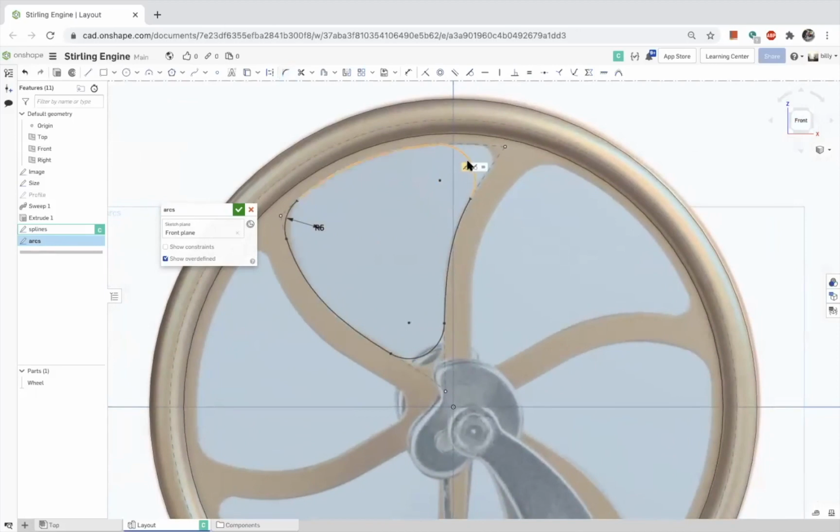With that, all you need to do is sit down here and click on it, and it just automatically made equivalencies. Okay, I defined them all at the same time. I can drag that down. You see how I can drag these arcs now? If that was all in one sketch, it's out of control. So break your sketches up. So there's that. Awesome. And in fact, I don't even want that.